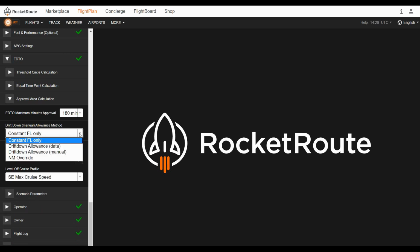Then moving next, the second one is drift down allowance. If there is a drift down profile provided by the aircraft manufacturer for your aircraft, our system will use it for the drift down calculation, as well as defining the level off based on mass and temperature. You just need to select what cruise profile should be used after level off. I have selected the single engine max cruise speed.